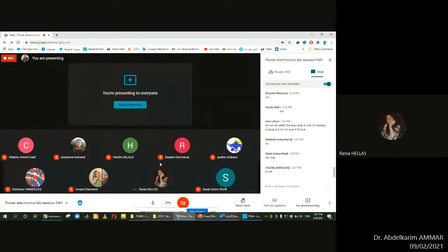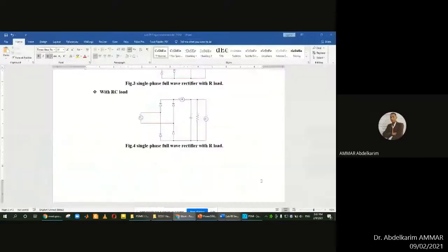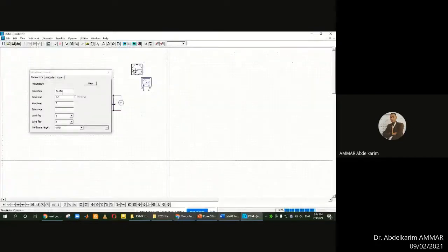Sir, I have a question. Okay, yes. How can we change the total time of the simulation? Because when I tried to do it, the simulation time was too long. The simulation time, okay. The clock. This is the clock, simulation control. Here we have total time.